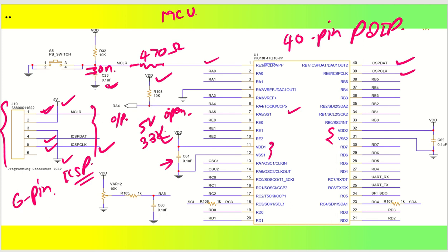One more thing I have done here is I have connected RF5 to a potentiometer. So for this 10K potentiometer, as it moves up or down, this node voltage will reduce or increase. This node voltage will be going to your RF5. RF5 is connected here, and it has ADC capability. I have told you almost all the pins have ADC functionality. So this RF5 will be acting as an ADC input, and this is how you can get your ADC value for the particular value of this voltage.